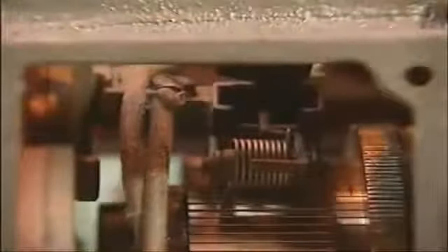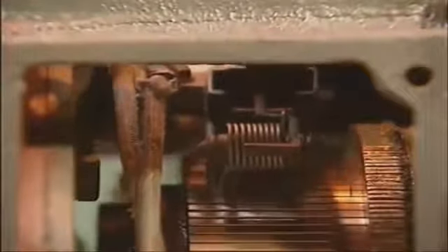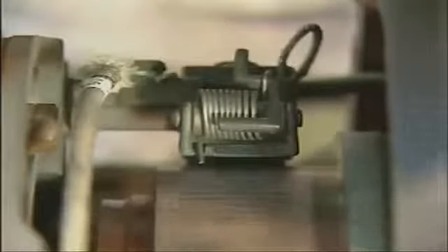Brushes make the electrical connection between the power source and the commutator in a DC motor. Brushes are usually made of carbon, and the size of a particular brush is determined by the amount of current it has to carry. Many of the problems that occur in DC motors originate in the brushes or in the brush rigging assembly. Two main causes of brush problems are wear and damage, both of which can be caused by improper adjustments.